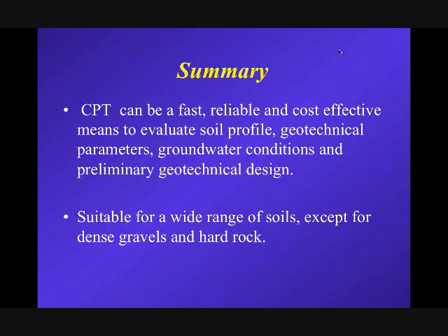And you can estimate the soil profile. You can get a wide range of geotechnical parameters. Of course, you can estimate the groundwater conditions, and not just where the groundwater table is, but actually determine the piezometric profile and determine whether or not you have artesian pressure and so on. And of course, you can do preliminary geotechnical design. And of course, also there are sensors for environmental purposes that we'll talk about in a subsequent presentation. And it's suitable for a wide range of soils, except of course very dense gravels and hard rock.